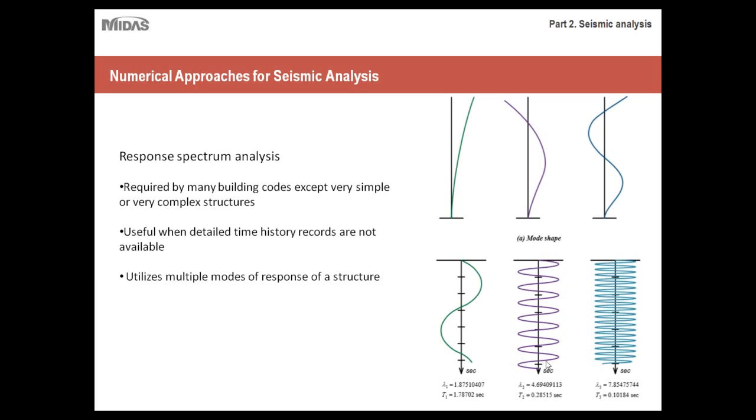Whereas when the earthquake increased in frequency and in strength, then you'd have a second mode shape that you'd run calculations for, and you'd assume that the forces would act in such a way. So for example, you might have a node here, you'd have a force acting this way, and then you'd have a node here, and you'd have a force acting this way. Whereas in the first mode, you'd only have one force acting this way. And then finally, maybe you'd have a third mode for critical conditions when the earthquake is at its strongest, and you have maybe three nodes this time with a force acting this way and this way.